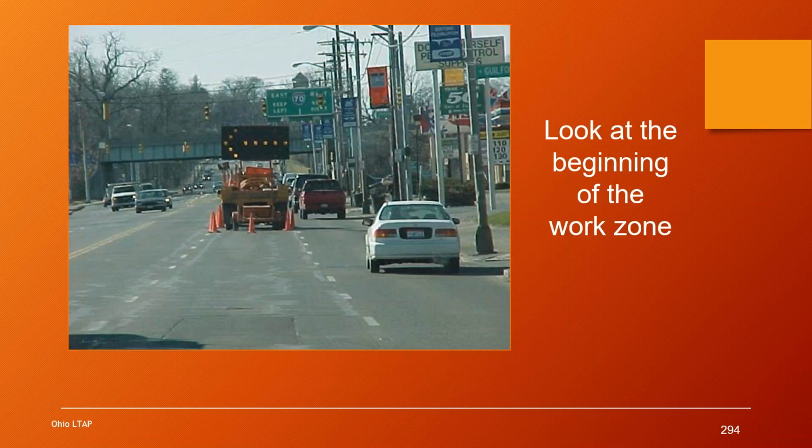And then in this picture, they're showing they have an arrow board, which is good, but with this particular arrow turned on, when the motorists see that, they think that they should get over here into the left lane. And this is a pretty interesting area on West Broad Street because you got a heavy right turning volume of traffic right here.